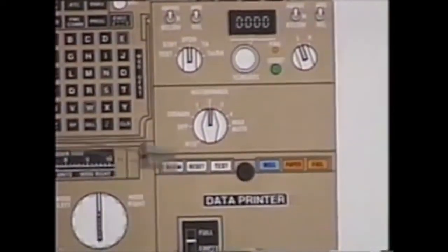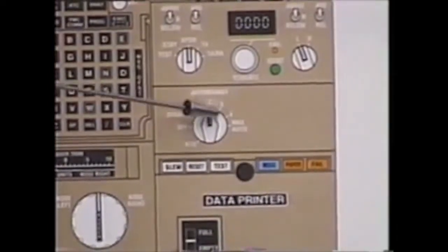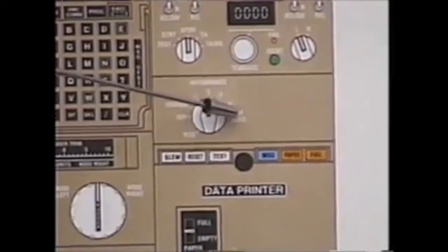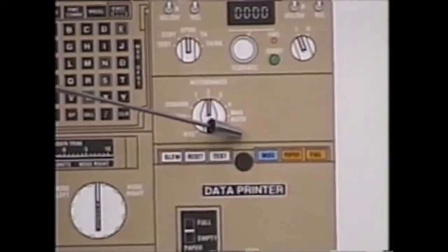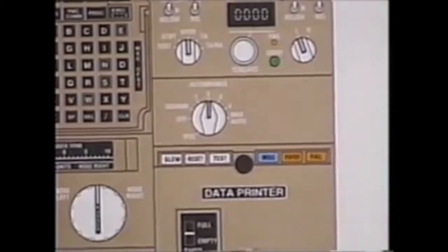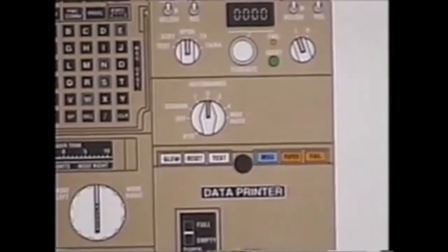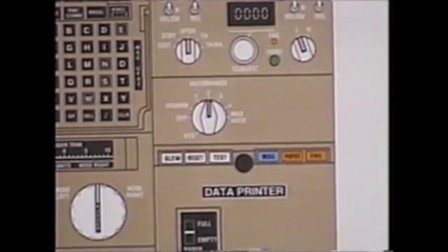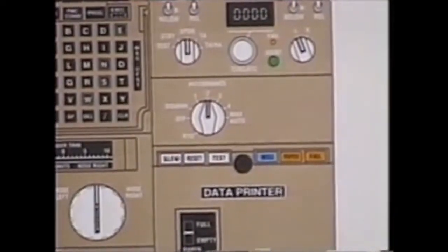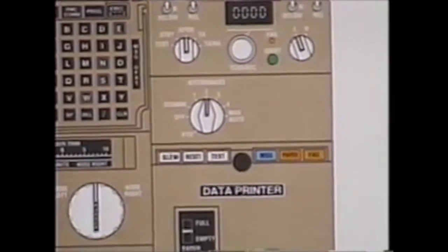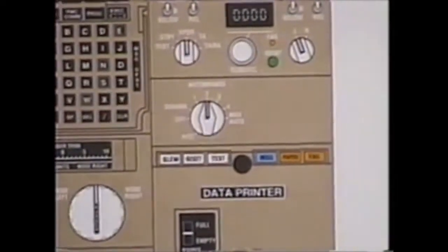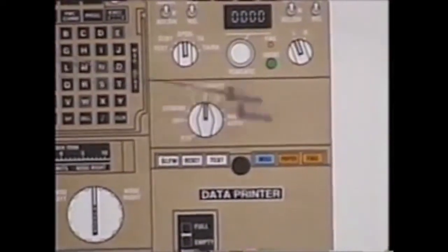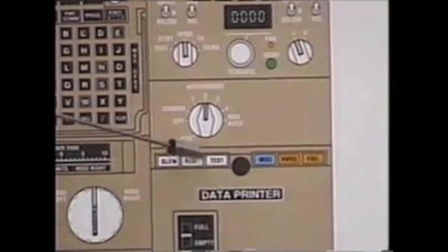If you land with this in any selection, example level 3, during the rollout you could increase to level 4, you could actually increase into level max, decide that's too much, and decrease. So after touchdown, you can increase and or decrease the auto brakes, provided you do not disarm it. Once you disarm the auto brake system, you're done. If the auto brakes are not armed at touchdown, please do not attempt to reach up and arm them. You can physically outbrake the max auto position. You cannot outbrake RTO.